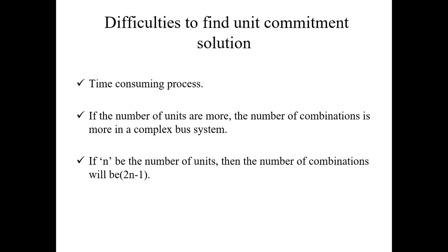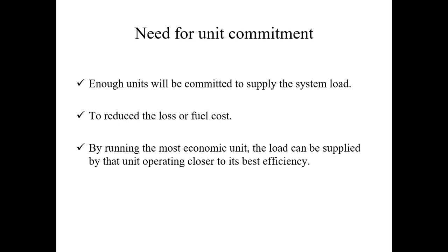And what is the need for unit commitment? This is a simple need, which allows a reduced cost or fuel cost. We have to reduce the total amount of cost as well as the losses. The losses include the transmission loss, operating loss, and similarly running costs. These are all the losses coming under the power system, and we also have to reduce the total amount of fuel cost. The amount of fuel consumed for generating the power has to be minimized.